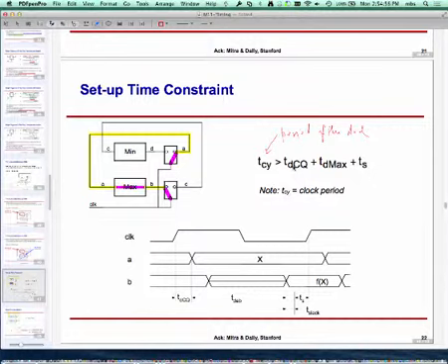So at some level, these numbers are not deterministic. They change from chip to chip. They change across temperature. They change with voltage. A lot of things affect them. So always you want to make sure that there is some margin that you leave so that unanticipated stuff can be handled.